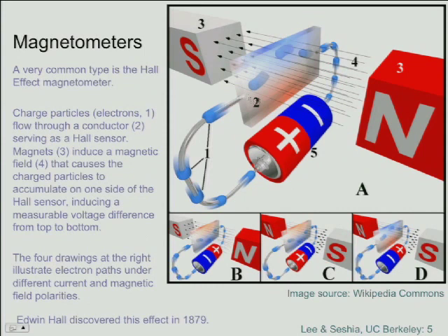Accelerometers. We're going to use accelerometers in the lab. The first challenge problem you're working towards in the lab is having a robot climb a hill. In order to climb a hill, it needs to figure out which direction to point in to head uphill, because it's not going to effectively climb the hill if you don't head uphill. So you can use an accelerometer to measure tilt, right?